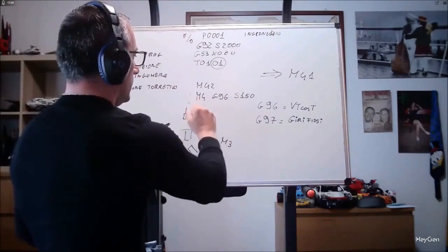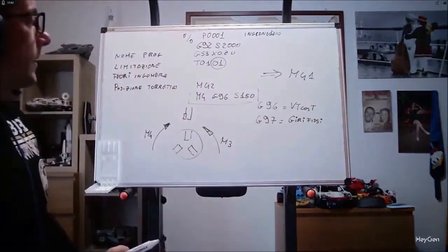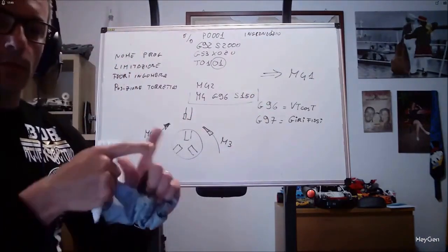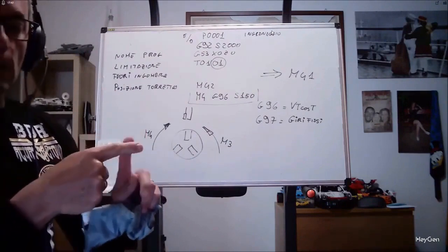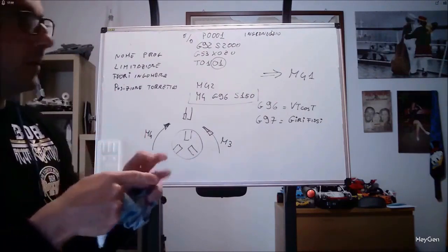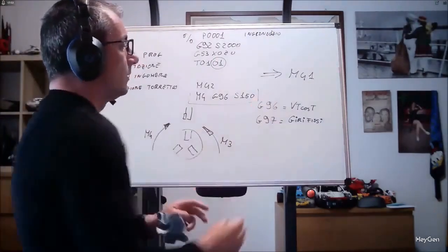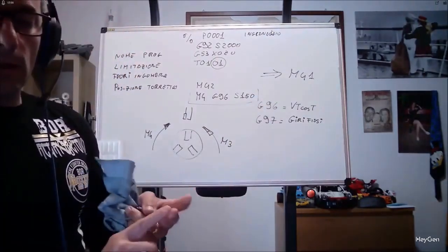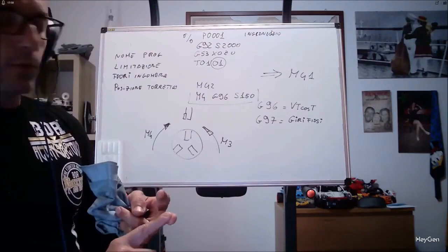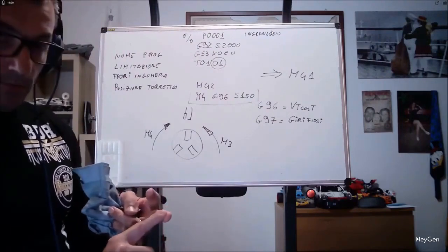So this is the command line to make the spindle rotate. M4, rotation direction; G96 or G97, constant cutting speed or fixed RPM. Then, to these two we communicate how many fixed RPM to use, or what constant cutting speed to use.